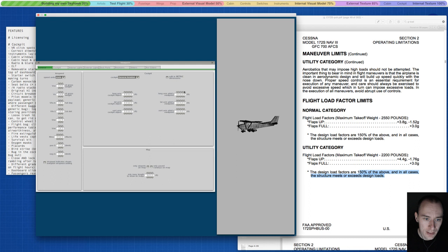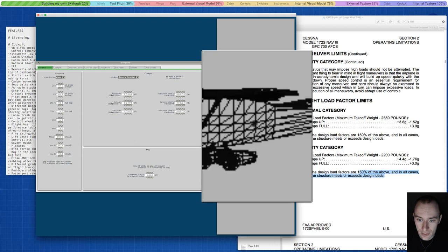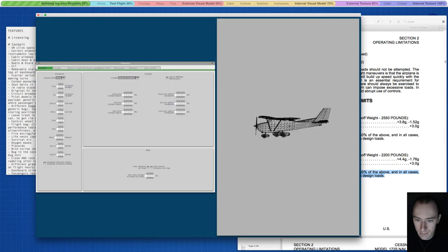Yeah, so this is the cockpit object and this is the viewpoint. So this is 000, and I guess in reference to our already existing reference over there. Does that matter? If our viewpoint is there, we won't see anything when we load up the cockpit with this current model because we don't have anything. So I'm thinking when we're turning or taxiing or stuff, I think it's safer to put it a little bit more in front. Let me see. Longitudinal. Does that change? Yes, it does. Well, in that case, let's just put the view right where I would expect it to be.